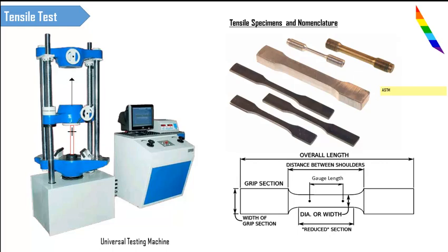So this elongation is measured by using an extensometer and/or by using a strain gauge, and these data are being fed to the computer. So those are the input data. For manual type of UTMs, there will be a dial from which we are going to measure the load, and we are going to correspondingly measure the deflection using the extensometer. So this deflection we are measuring is in between the gauge length.